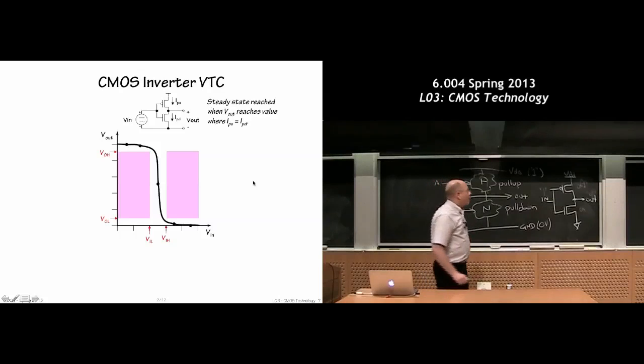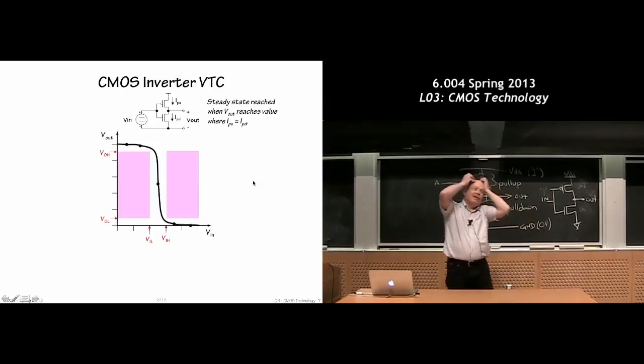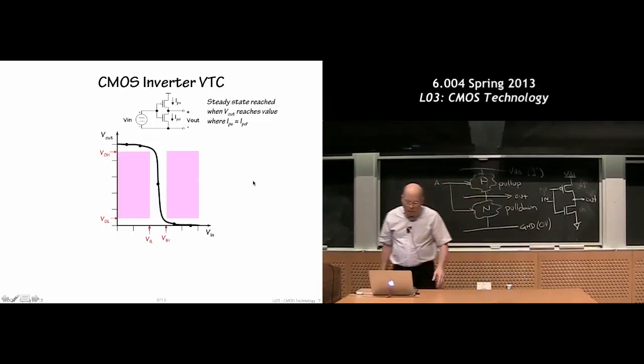So as I'm designing these pull-up and pull-down networks, if I want them to behave as logic gates but never create a short, what do I have to guarantee? Well, that they're never both on at the same time. That would be a real disaster. Or if they're on at the same time, they're only on for very small fractions of a second, a picosecond or two. So when I design these networks, I'm going to have to design them to be complementary. If one is on, the other is off, and vice versa. That's the whole story behind complementary logic.